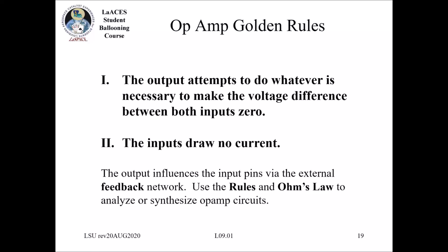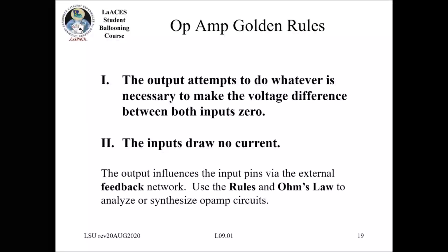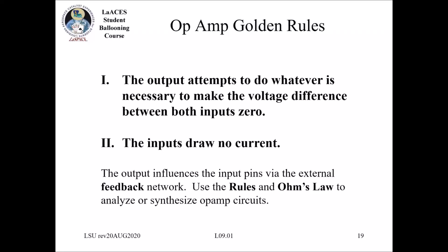This is often done whenever you have what is known as a feedback loop in that circuit, and we'll see that in a moment. And also that the current into the operational amplifier inputs is 0. Now, in reality, there actually is a very, very small current that goes into the operational amplifier inputs, but it is very small, and for the applications that you guys are going to be using it for, it should not impact your sensors or your signal conditioning.